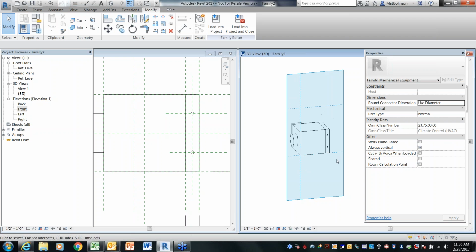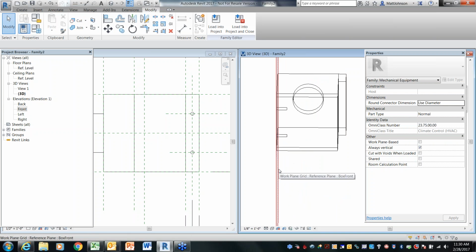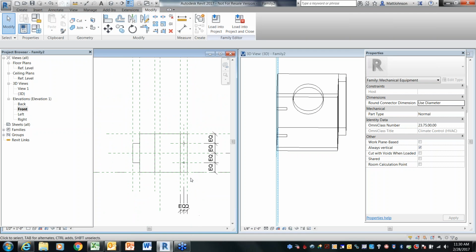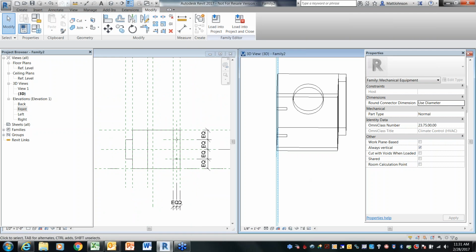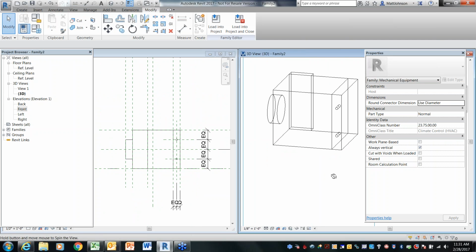Okay, so we turn this around, and again, it did the same thing. See how it threw the pipe, it attached to the correct work plane, but the normal's off, so it shot the extrusion to the inside of our box, right? No big deal. We just want to go to the right-hand side.